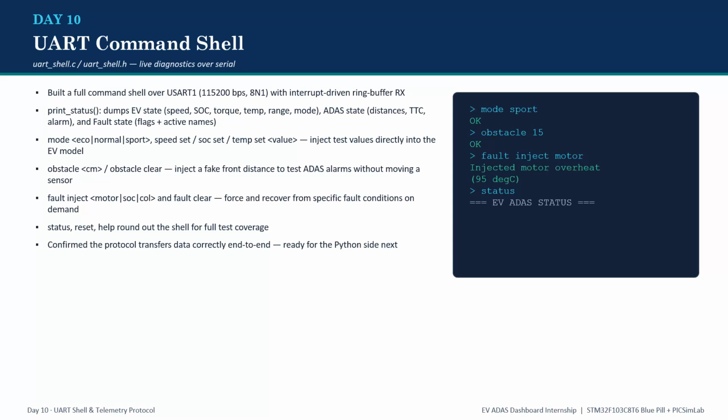I can force specific faults with fault inject motor, or fault inject SOC, or fault inject collision, and recover with fault clear. And there is a general status, reset, and help command rounding out the shell. By the end of day 10, I had fully tested the UART protocol, ready to transfer data reliably. The next step, which I did right after, was writing a Python script to receive and visualize all of it.